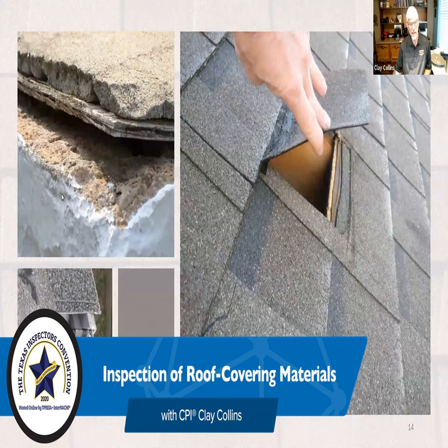Now you see in the middle picture up here, not only has there been repairs, but there's been additional damage. And it looks to me like this was abrasion by overhanging limbs. And it was bad enough to do some repairs, but apparently not bad enough to repair everything that was damaged, or there were additional repairs. Or maybe they only had so many shingles to work with. It's just kind of hard to say. And on the right, I think we see this all the time. That is where a satellite dish used to be.